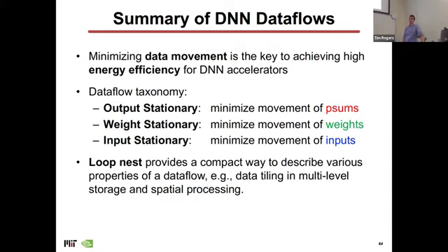And then some of the hardware design is around all these other issues. Sparsity is really hard to deal with at the compiler or software level because it's dynamic in some ways. And picking the right bit width is very hard to deal with at the software level because maybe you need different bit widths at different times. The mappings of trying to keep things inside storage structures are usually better suited to software than accelerators.